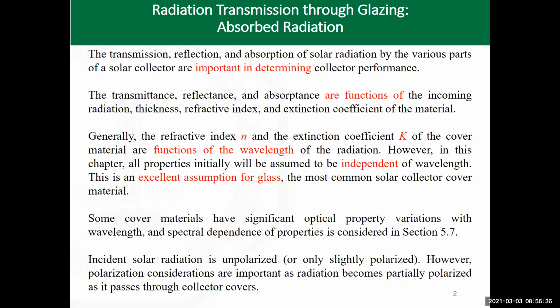The refractive index and the extinction coefficient of the cover material depend on the wavelength of radiation. Although, for the sake of simplicity in this chapter, we are going to consider them as independent of lambda. The dependence on lambda is not significant, especially for glass, which is the most common type of solar collector cover that's being used in industry.